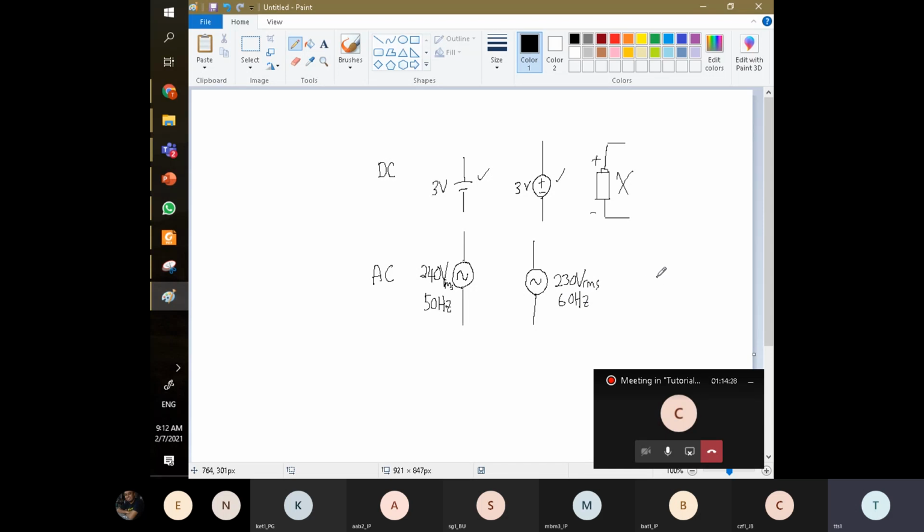And for China, I remember it is 220. That's why when you buy China electrical appliances, sometimes they are designed for 220 only. Malaysia is slightly 20 volt higher than China. If you buy appliances in Singapore, it's 10 volt less than Malaysia. So most of the time they won't last as long in Malaysia because our voltage is higher. It puts some stress on the components.